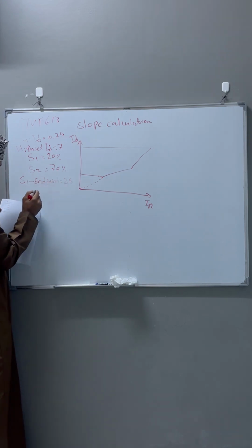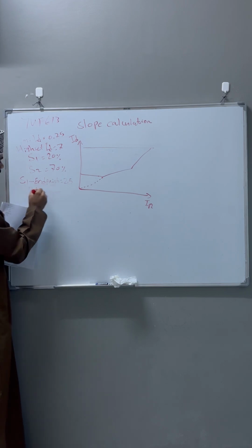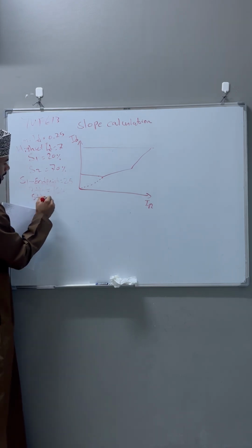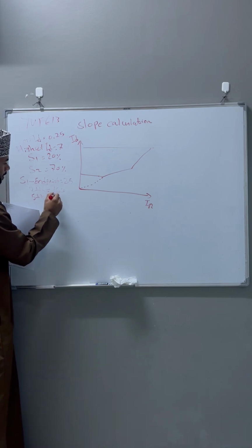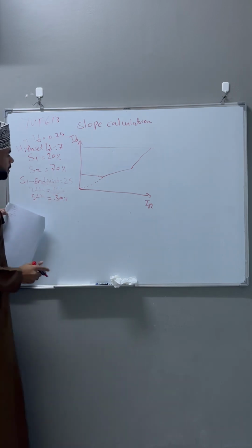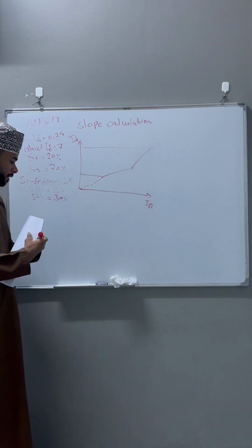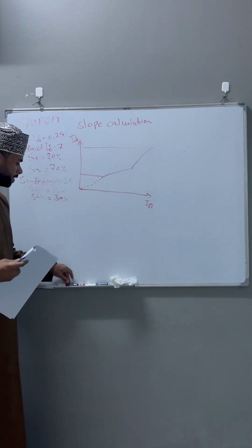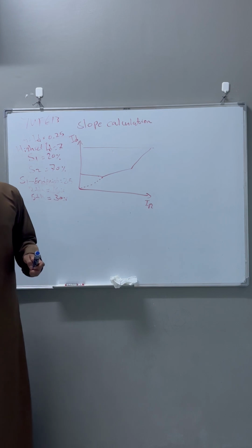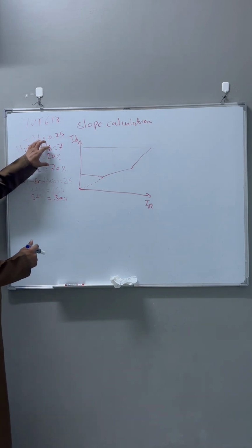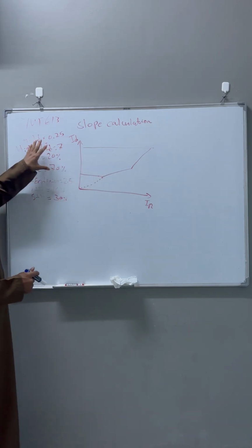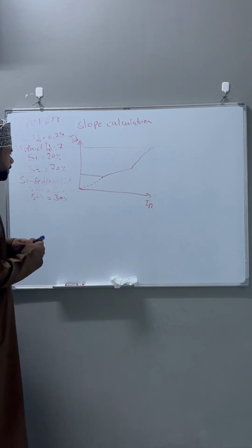Okay, also they gave me the second harmonic and the fifth harmonic. Second harmonic 50% and fifth harmonic 30%. So they gave me these settings. It is a real example from the last transformer differential relay I tested. Now let's implement the settings here in the graph. Okay, let's implement the settings in the graph here.